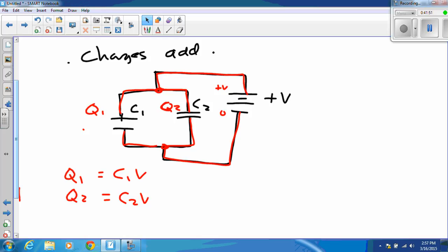To make these in parallel, I have to get them both hooked up to the same connections on both ends. So I have this one hooked up to that one on each end, like that. Does everybody see how this works out? There's a connection there, because these are all in the same row. And this is connected to the negative power bus. And these two are connected because they're in the same row and connected to the positive power bus. Okay? Turn this on. Do some voltage measuring.